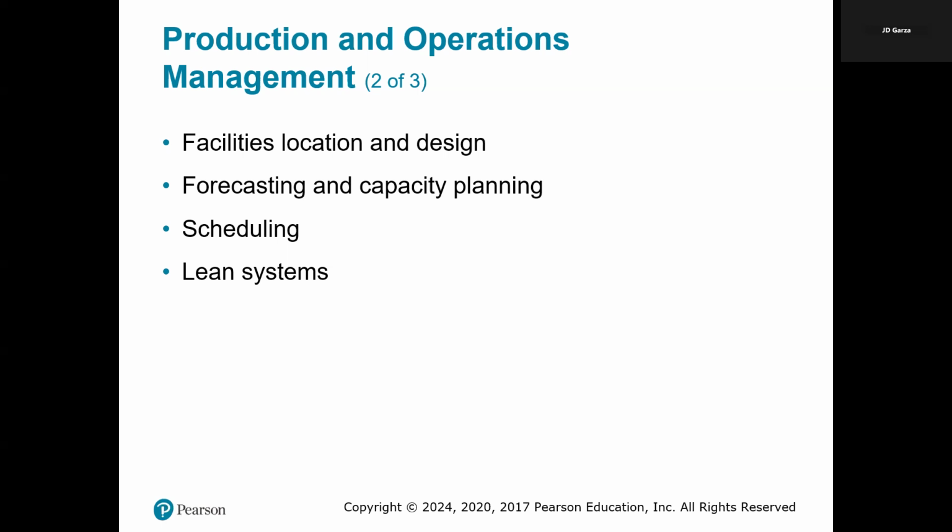Okay. So this lean system includes minimizing unnecessary movements, reducing waste, also reducing waiting times, or even eliminating defects in products. Now, the concept of just in time, remember that word too, just in time, JIT, is a key part of lean systems. Producing only what is needed when it's needed, thereby reducing the excess inventory and costs. Let's just say, as an example, Toyota, a pioneer of lean manufacturing, produces vehicles based on customer demand rather than preset production quotas, resulting in lower inventory costs and higher efficiency.